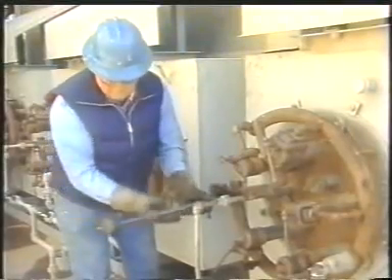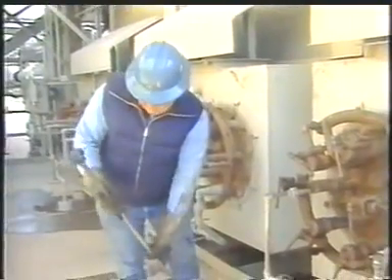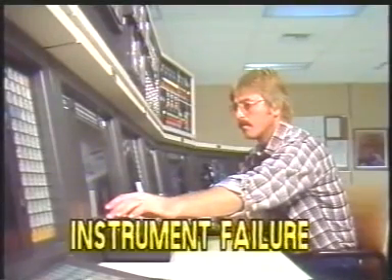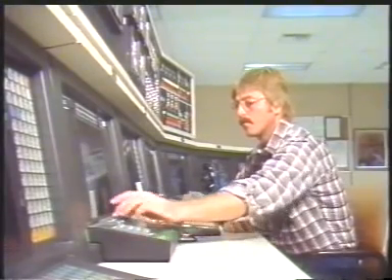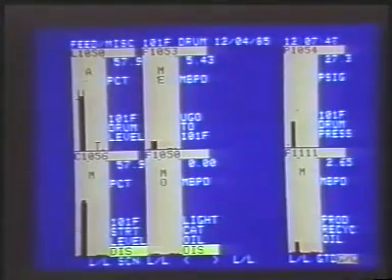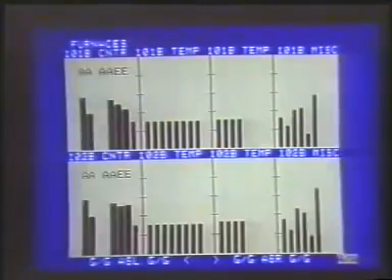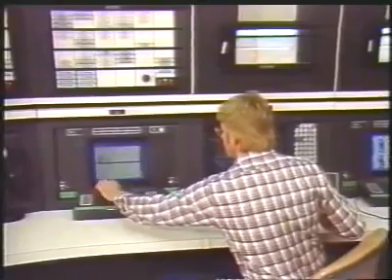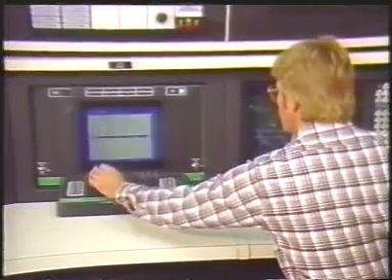The furnace burners can also break down. Burner failures are often caused by plugging or fouling in the burner tip. If a burner fails, you'll need to remove it from service for cleaning or repair. Instrument failure is not always easy to detect. The operator must understand the interaction of variables in the furnace to judge whether a particular reading is accurate. If the furnace has automatic controls, the controls may try to correct a situation which doesn't exist. If this happens, the operator must take the controls off automatic and manually adjust the operating variables. Correct diagnosis and quick reaction can often prevent a furnace shutdown.